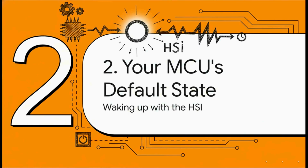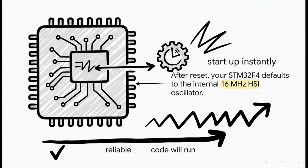Okay, so to figure out how to speed things up, we've got to know where we're starting from. Let's take a look at what's happening inside that chip the very instant it gets power. And there's a really smart reason for this. The folks who designed these chips wanted to make sure your microcontroller could start running your code immediately, no questions asked, without needing any external parts. That's why it always defaults to the high-speed internal oscillator, or HSI. It's a 16 megahertz clock source that's baked right into the silicon.